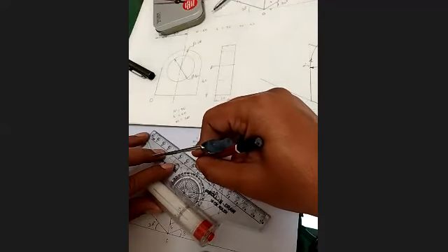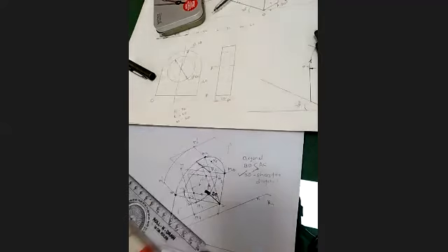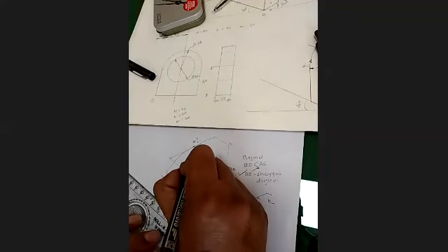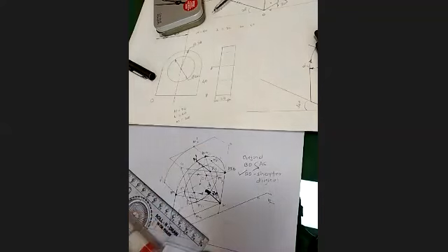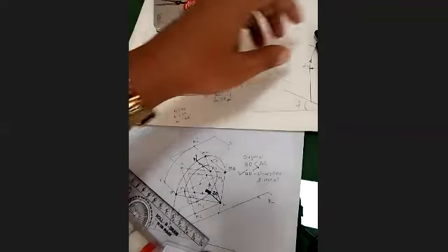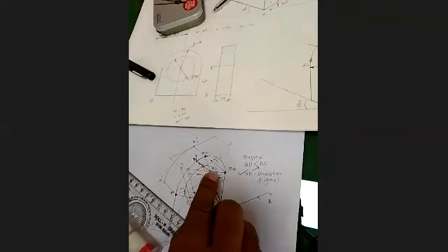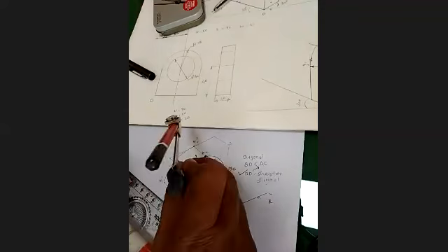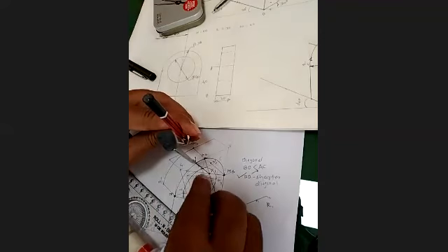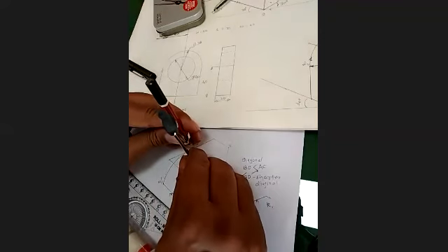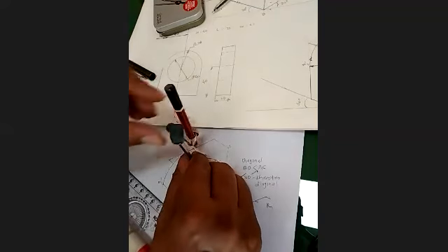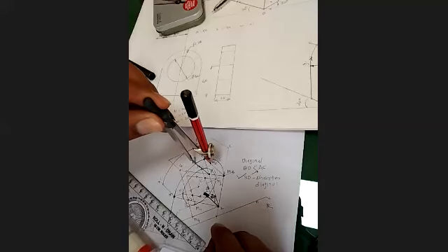10 and 20. Now this is the P point, P1. So I can say this is a P1 dash point, right? So from this point, I have gone 20 millimeter back. Now you will be taking the radius P1 to M2, the same distance you are going to get here. So you take the distance P1 to M2 and draw an arc which is going to join with the M3.